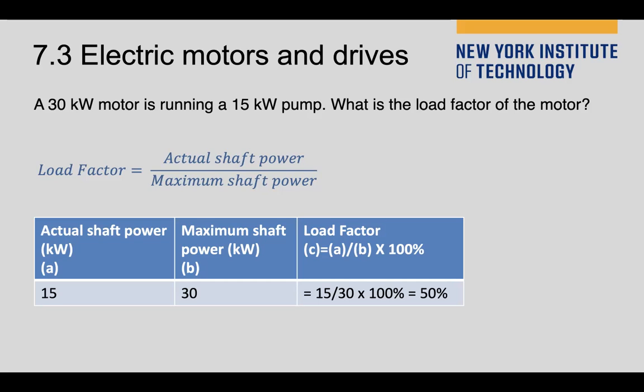So all the times we will think about the duty cycle of the motor is how the motor operated. You need to continuous one for a very long time. For some of the application will happen like this. But for some of the application, it may turn on 5 seconds, turn off 5 seconds, turn on 5 seconds, turn off 5 seconds, or turn on 5 seconds and stop for 10 seconds. Is a kind of duty cycle.